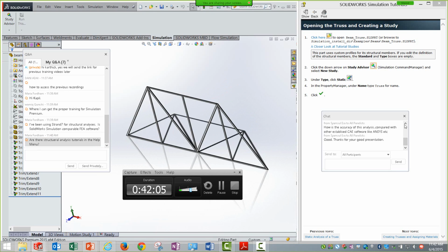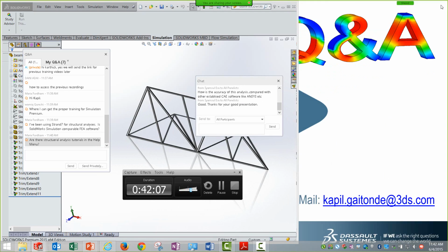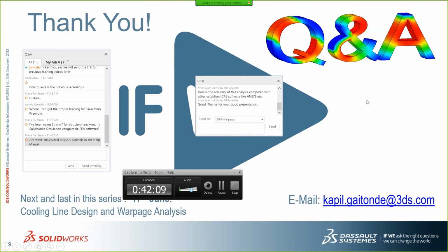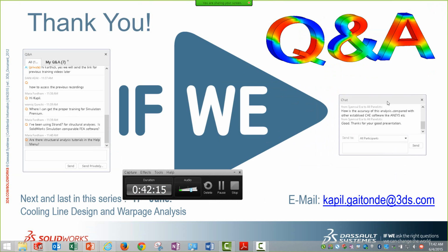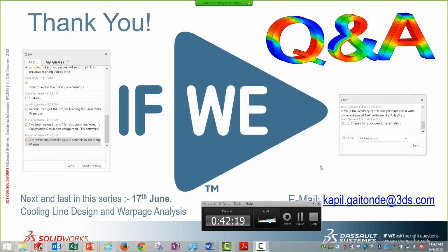Our approach is, we have something called weldments in SOLIDWORKS CAD. Those get translated into beam elements automatically. So you need not waste your time creating these beam elements and doing nodes, elements, etc. As well, the cross section can come from the 3D. Results can be visualized in 3D. So those idealizations can be done. And yes, the online tutorial has it.